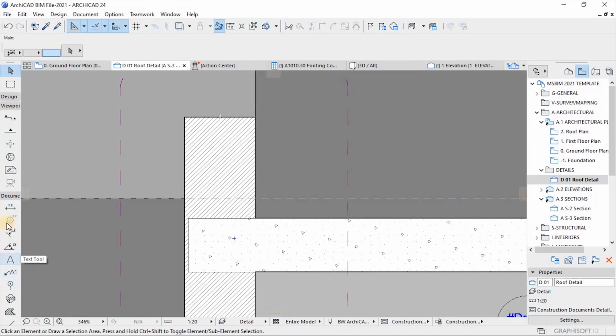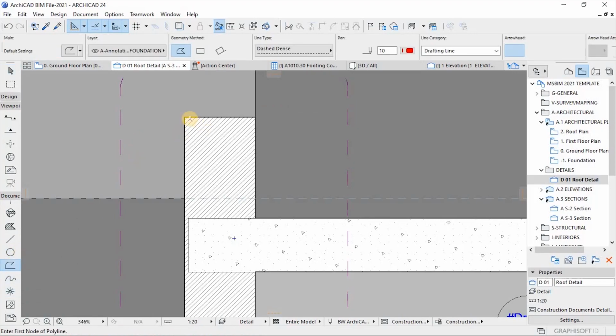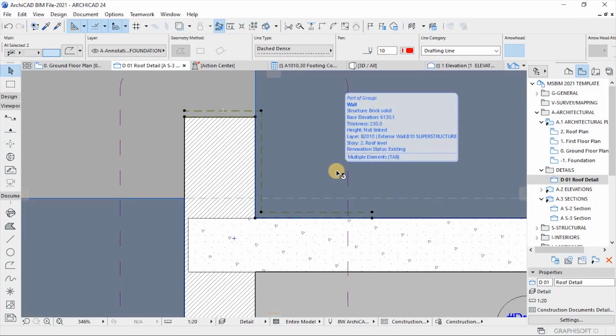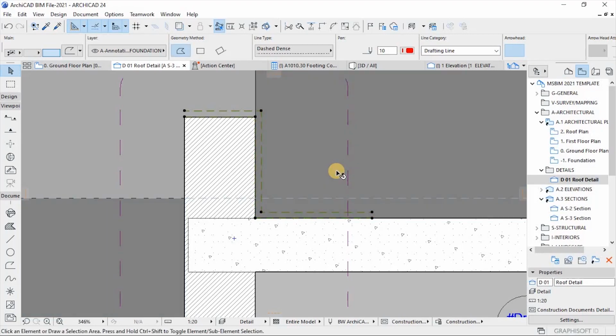So I'll use 2D information. Go to documents, let's pick the polyline. I'll draw a line like that, just like that, maybe there. And then what I'll do, I'll click on this, click on the corner, offset this. To add a copy, I'll hit Control on the keyboard, and then this will be 20. Perfect. Now I'm going to copy these two guys. I can just cut, Control X to cut.